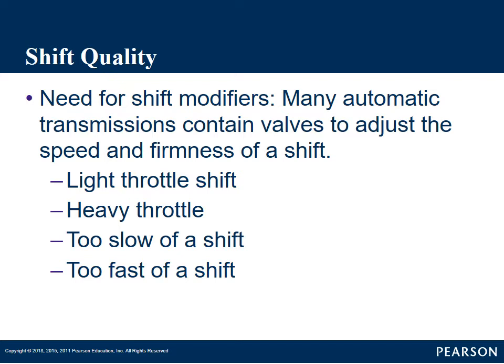So that is the balance that the manufacturers try to find when building these, and when we're rebuilding those, we try and find a way to firm the shifts up, repair any defects caused from wear on the original design, and we try to find a way to maybe firm up the shifts, shorten the shifts, without making them too harsh to where the customer complains.